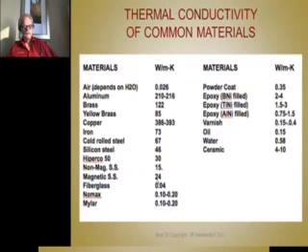Fiberglass is not that great. Magnetic stainless steel, so-so. Non-magnetic stainless steel, Hiperco 50. This is a lamination material. Silicon steel, cold rolled steel, iron. It's all getting better and better, as the metallics are certainly better than the plastics or the hydrocarbon materials. So it's good to have those in mind. Varnish. Oh, the varnish is here. Varnish is the same as the enamel that's on the magnet wire itself. That's not very good either. Some of them are filled with some solids, which kicks them up a bit. That helps a lot.